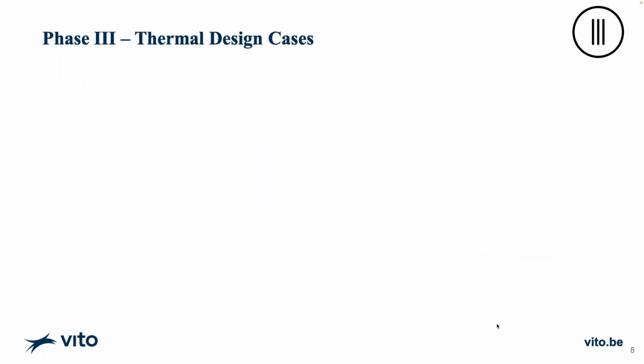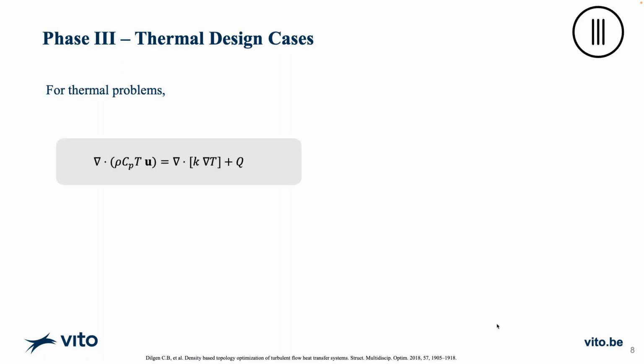And with this, we go to our final phase, which is including heat transfer. So we look at the energy equation. We introduce the modifications where now your thermal conductivity is also a function of your field variable, porosity. And what we do is that depending upon whether you are in the fluid or in the solid, you change your thermal conductivity.